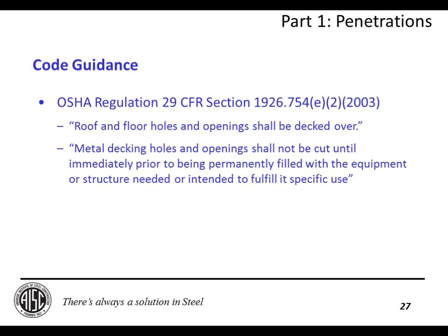So OSHA regulation is essentially common sense. It says that your roof and floor holes and openings shall be decked over until essentially immediately prior to being opened up for whatever pipes, etc., need to go through them. And this is simply a safety consideration for the workers. They don't want to step through a hole.